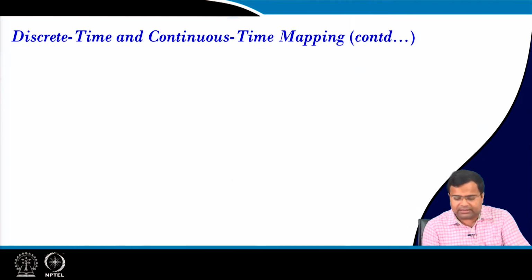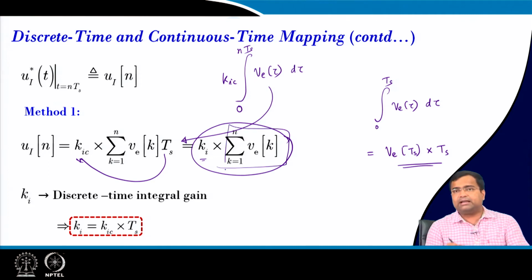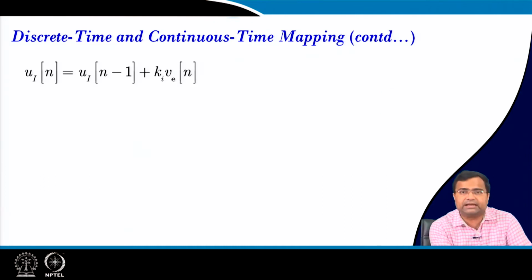So, this you cannot implement, because it will be accumulated and it may saturate your storing element, because in digital control we generally use a memory block, so it will saturate. So, we need to use an incremental method or basically an iterative method.